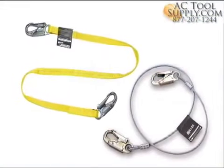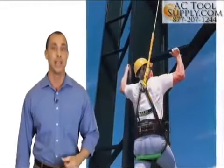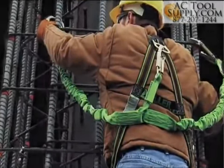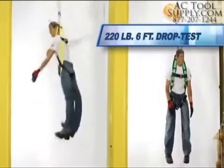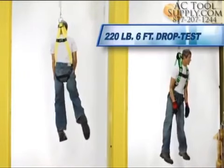While both will arrest a fall, the maximum arresting forces when used together with a full body harness needs to be less than 1,800 pounds. This is extremely difficult to achieve using a lanyard without a shock absorber. A test fall of a 220-pound mannequin dropping 6 feet with and without a shock absorbing lanyard demonstrates the forces on the body.